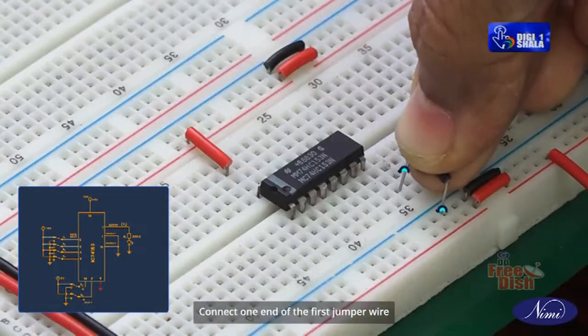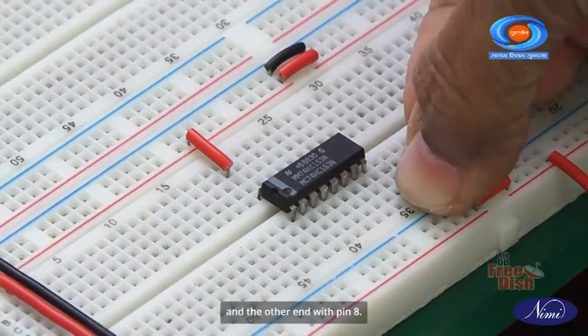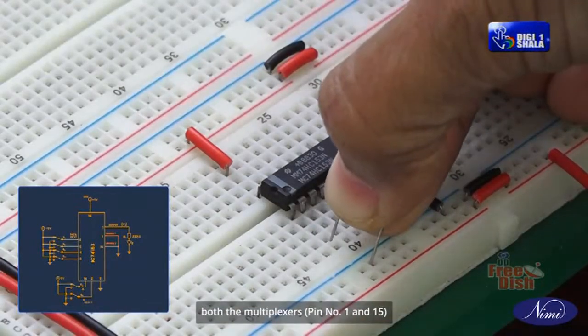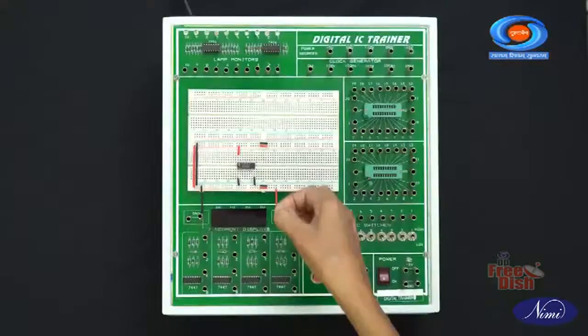Connect one end of the first jumper wire to the ground rail or the ground source and the other end with pin 8. This step is essential for powering the IC and providing a common reference for the circuit. Make sure the enable pins of both the multiplexers, pin numbers 1 and 15, are in active low state.